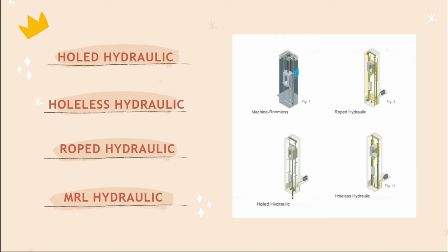Second is holeless hydraulic. Since a drill hole is not necessary, existing buildings or areas where drilling is not an option can benefit from a holeless hydraulic elevator. However, these models are not suited for more than 40 feet of travel.